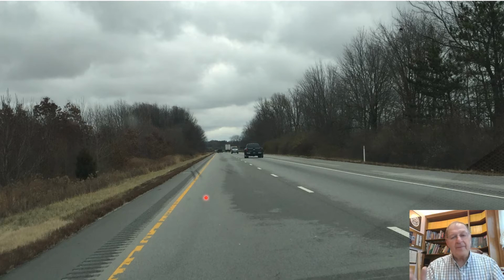And what happened here? I don't know. I can only speculate, but I can say one thing for sure, and that is that this pavement with higher in-place air voids will start to fail and come apart faster than these areas that have lower in-place air voids.